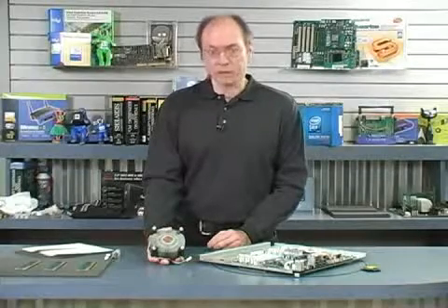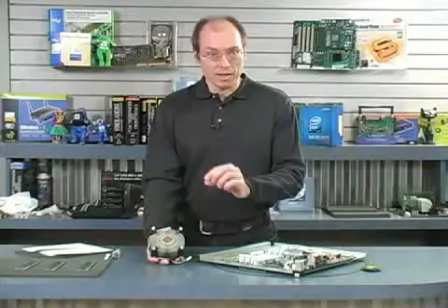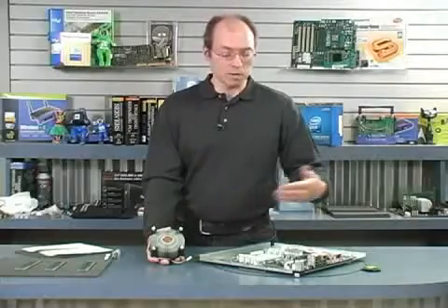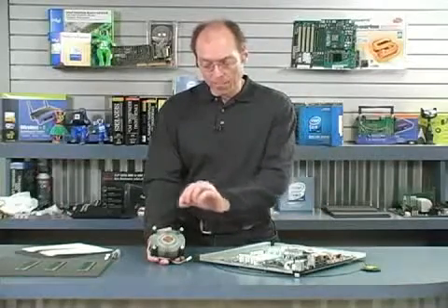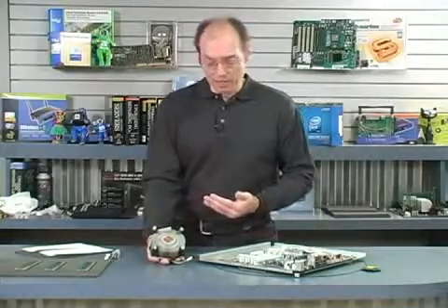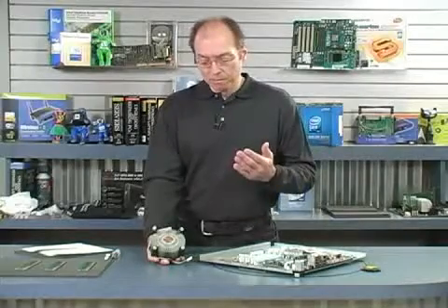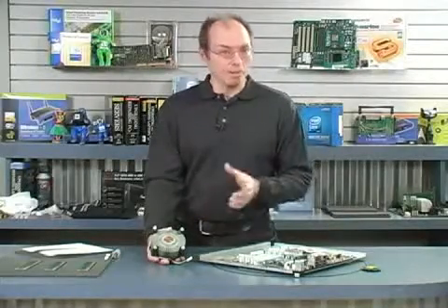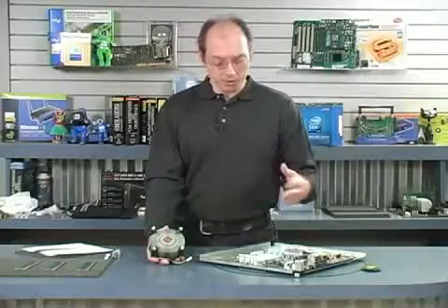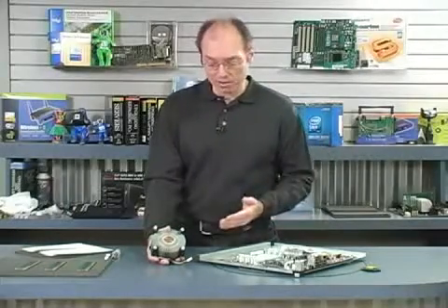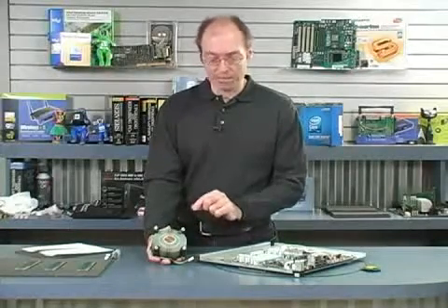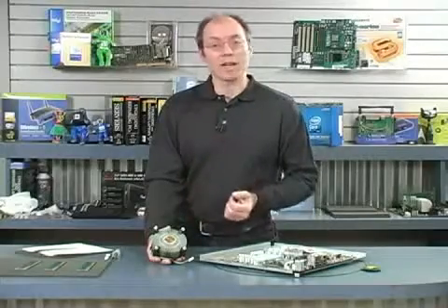Phase change material is a wax type substance that is a solid at room temperature and which then melts at somewhere over 113 degrees. So when the processor warms up, this stuff will melt and then liquefy and perform as it should. When companies like Intel and AMD deliver their boxed processors with the factory included heatsink, to make the installation as easy as possible, they will pre-apply a phase change type thermal interface material to the bottom of the heatsink. I'm going to show you an example on the screen right now of what that looks like.